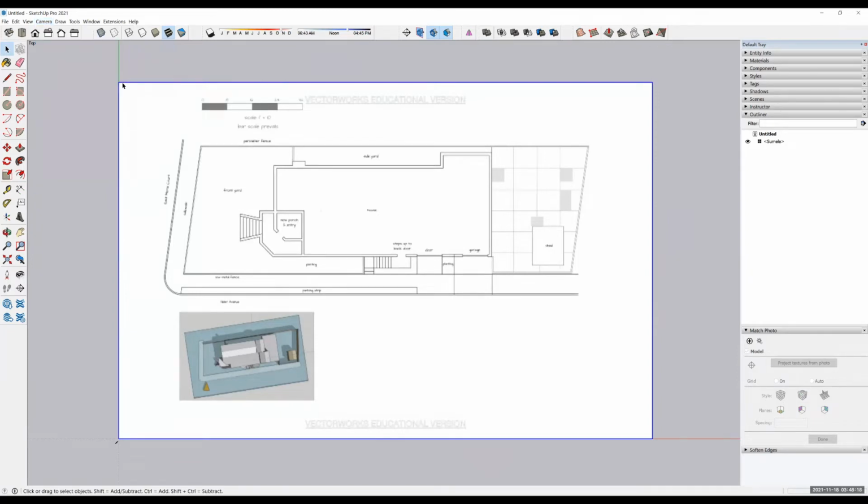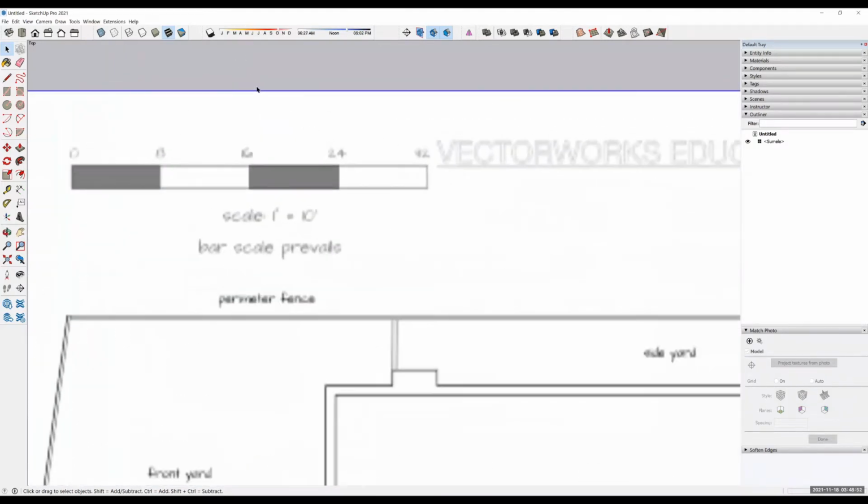Here you see I got a scale bar. Usually for the site map, there are two things we need to adjust: one is the orientation and one is the scale. So look for a scale bar. This is great. If you don't have a scale bar, look for some known dimension. For example, I know this building from this corner has a total length of like 100 feet, so I can just use that known dimension. For this one, we're lucky to have a scale bar.